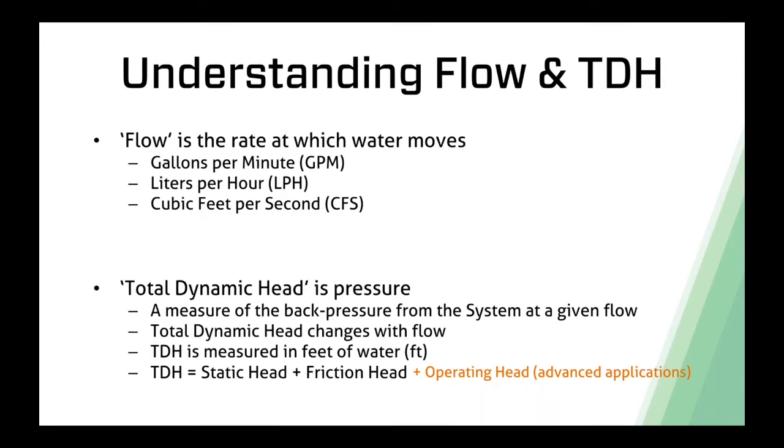But if you think about terms that you may have heard in looking at the weather, they often talk about barometric pressure in millimeters of mercury or inches of mercury. And what that's measuring is a very similar kind of a concept. Feet of water, it's measuring the pressure associated with a particular depth. And you could convert that to PSI if you needed to. But the main thing to understand is feet of water is not necessarily a length, it is a measure of pressure.